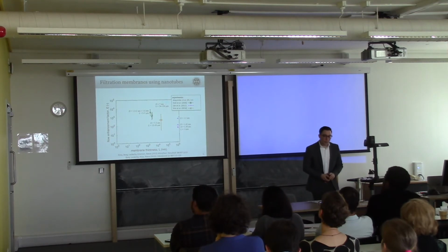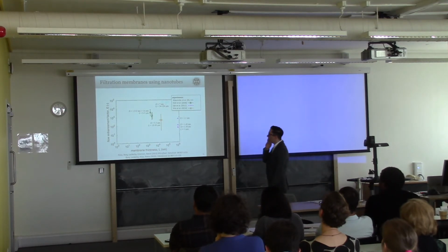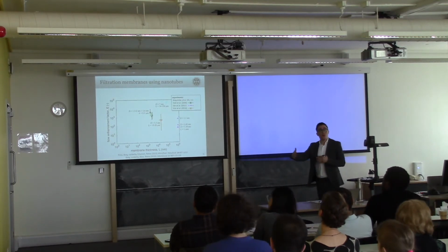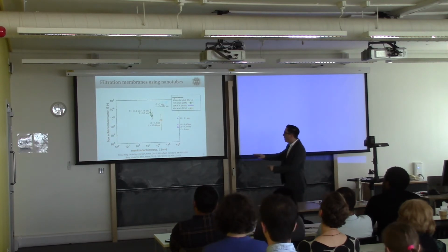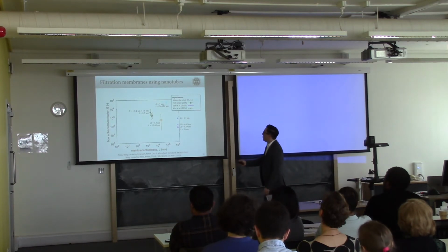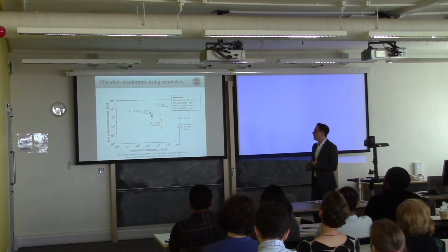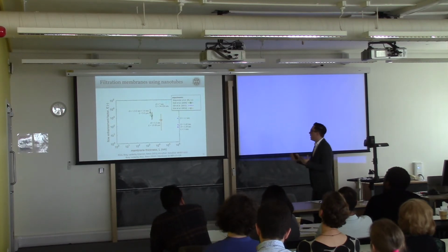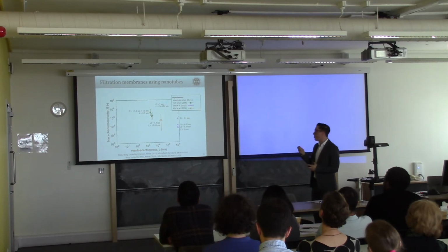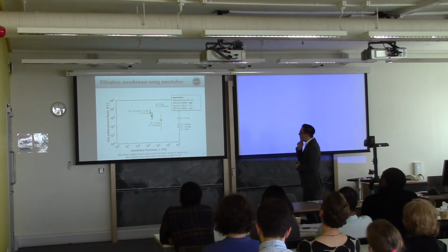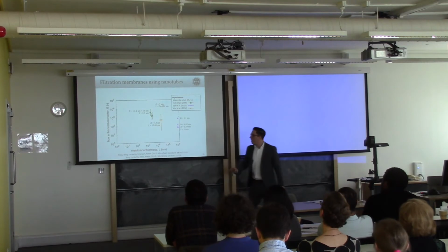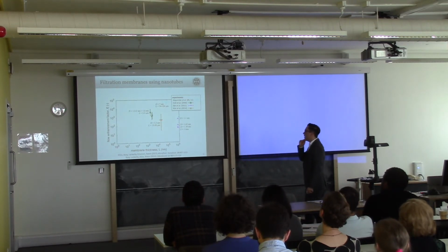Okay, so what I'm showing in this graph is, the y-axis is that flow enhancement factor I described, which is how much more flow you get through the tube. And the bottom one is the thickness of the membrane. So these are all experiments, and when we started compiling this, we started worrying about why these are so dispersed, and it's in fact what's driven us to do these multiscale simulations. With MD you can only arrive somewhere here, and so we wanted to see how our multiscale methods fare.